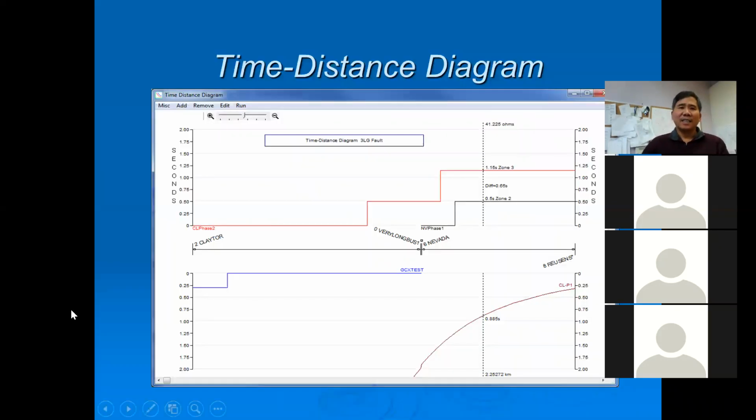I don't have it in the demo, but I do have this picture here that I can show you. In this picture, what we have at the relay position is a phase relay that has zone 1 covering about this much. I know this is zone 1 because if I look across, I see it tripping in 0 seconds for faults spanning this line up to here.